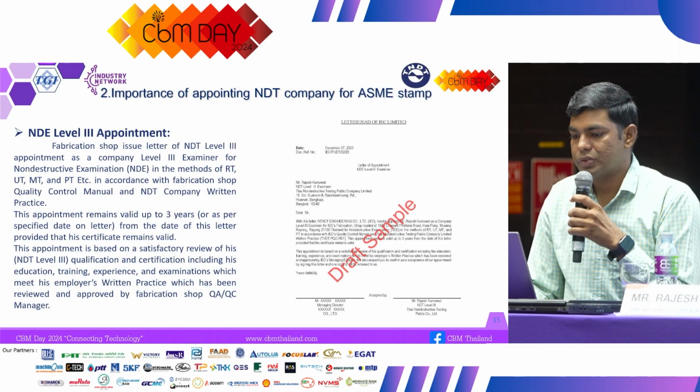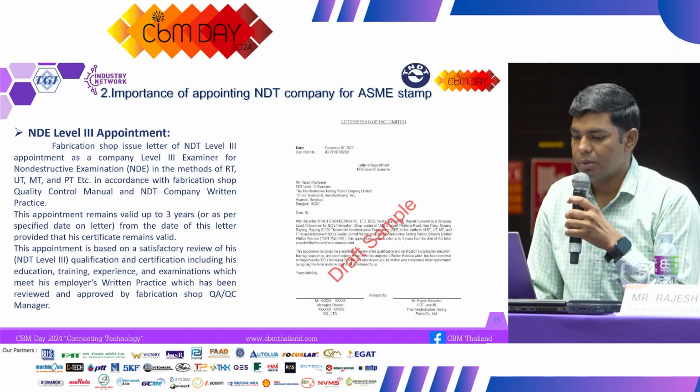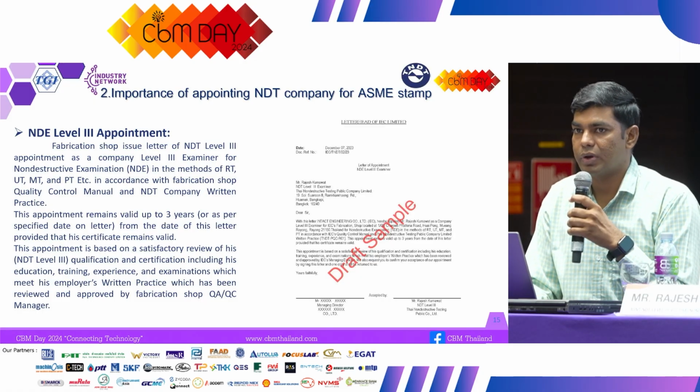NDT Level 3 appointment. If it is an ASME stamp, then the NDT Level 3 needs an appointment letter from the company, like this sample. The company's quality manager or someone can issue this letter, based on which methods the company applies: RT, UT, PT, MT. And this appointment validity may be 3 years or 5 years. The quality manager can check the Level 3's qualification, certification, education, training, experience, and examination to see that they meet the employer's written practice or quality manual, so both comply with the requirements.